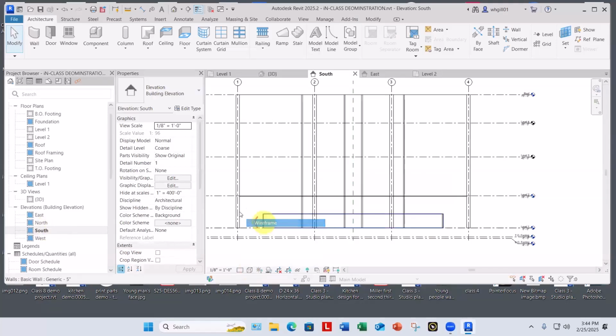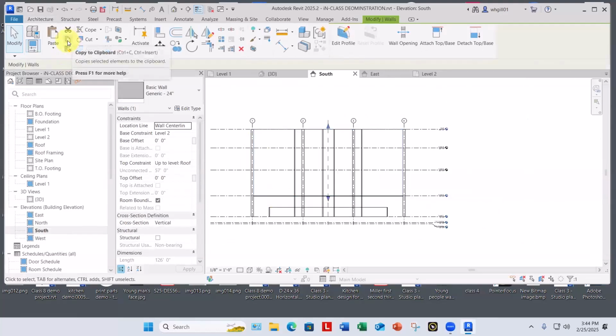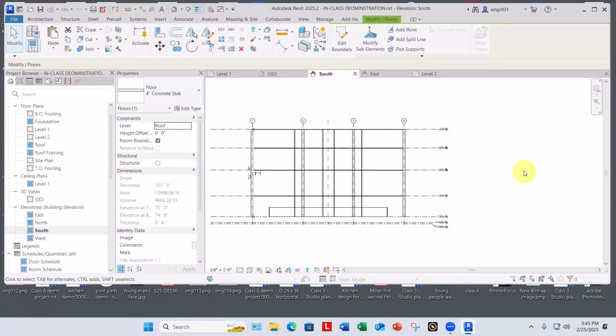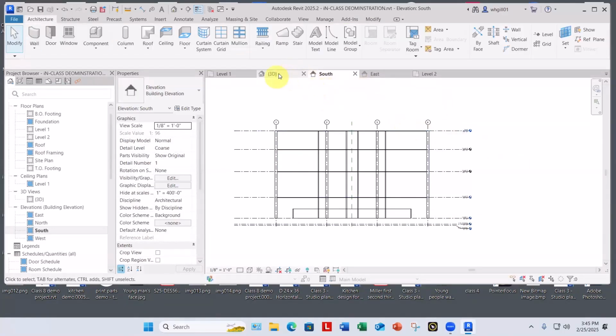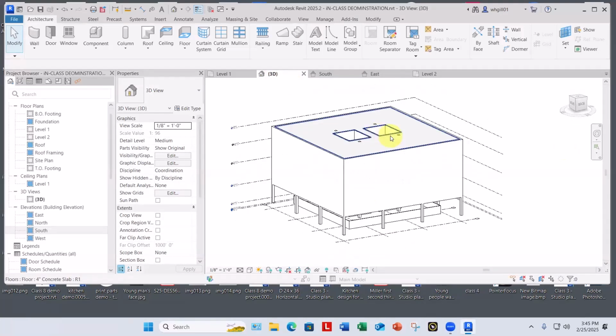Here I am in a wireframe view. Here's my level 2 floor. I'm going to copy it and paste it to selected levels, meaning 3, 4, and roof. It will just copy them to where those levels are. And you see this floor comes up with the holes cut in it already. And once we put windows in, we'll do the same thing with them, get them on the second floor and just bring them up to the other floors.